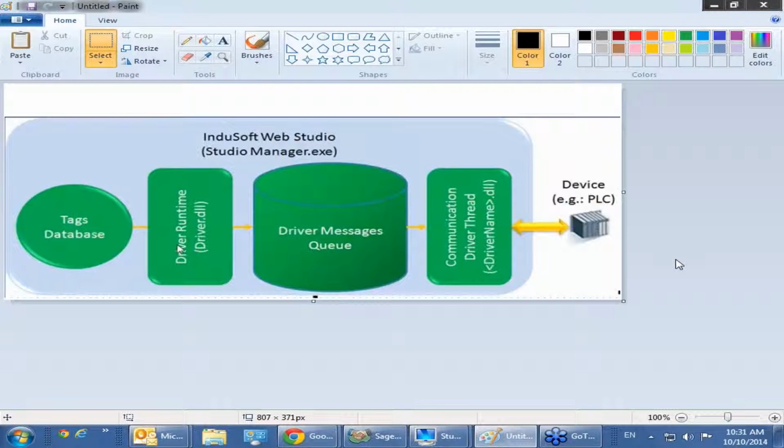If you're pairing with one module, you would just move one of these switches up, and this is to set the ZigBee PAN ID and the ZigBee channel. And then that's it, actually. The ZT2551 is a slave converter. Let me pull that up. And Maria, the rotary switch is for the Modbus address, the most significant bit.